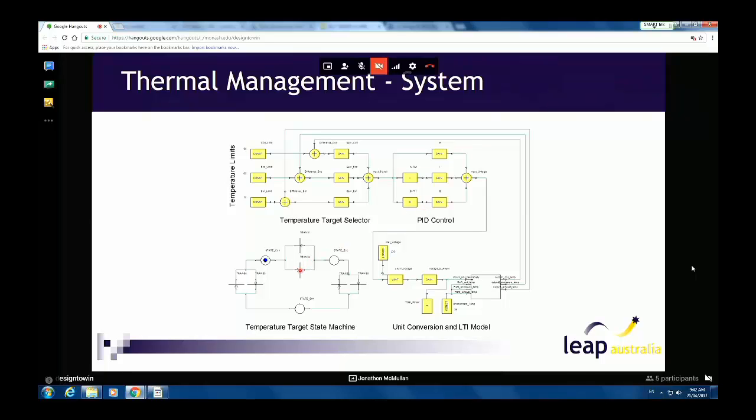And then we have the state machine here, which cycles through showing which of these is the high priority we want to look at. So for example, if we're closest to the coil limit of 90 degrees, then this is the difference that we want to look at to control the system. If we're closer to any other two, we want to swap.